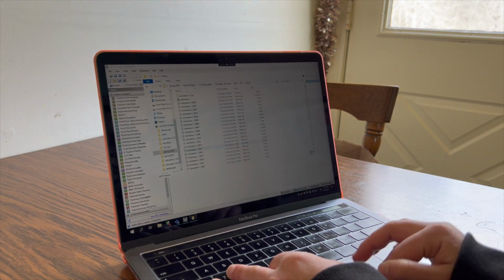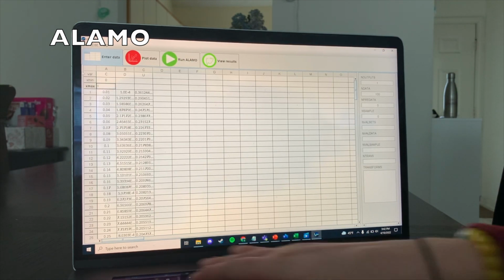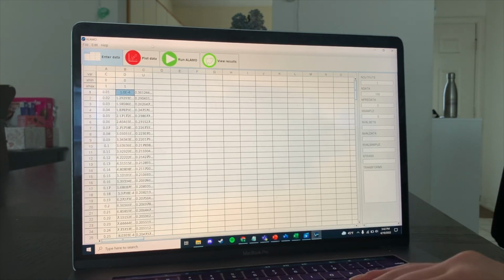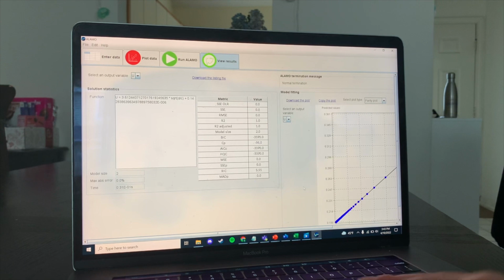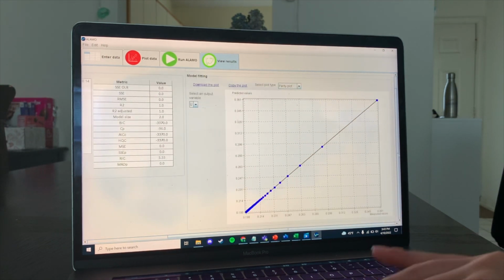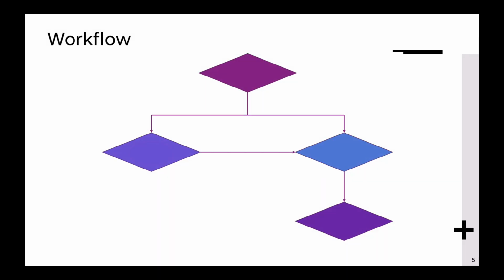The second software we are working with is ALAMO, which stands for Automatic Learning of Algebraic Models. It uses machine learning methods to create algebraic surrogate models between the inputs and outputs of a black box system. In our case, however, this is a glass box system, meaning we can see the behavior occurring in the system, but still need to figure out what's going on within it specifically. The glass box system our group is working with is the relationship between separator geometry and efficiency. We want to be able to manipulate design metrics to maximize separation efficiency.